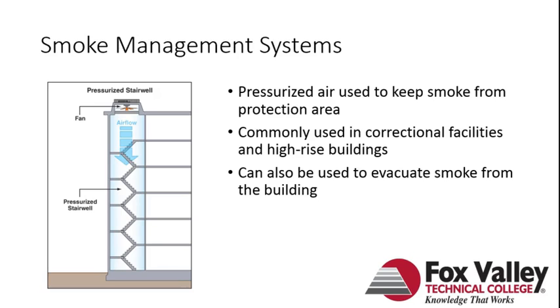If you look at your county jail, you don't have a giant yard to take the prisoners to. They have to go someplace in the event of a fire. What they'll do is get them into a stairwell. They pressurize it in this way so that the smoke stays out. Actually, at this point, the guards will don SCBAs, and then they'll keep the prisoners there. So it works in a couple of different ways.